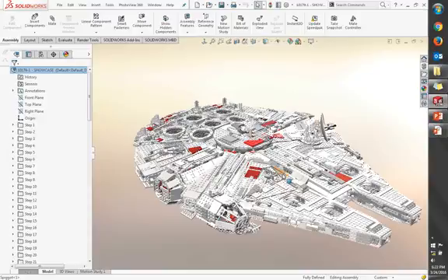So what I found out is that it's not so much a piece part count that you really run into. Really it comes into the mate count. And on this particular computer, when I get to about the 3,000 to 4,000 mate range, I see my computer take a huge dump. Now, 3,000 to 4,000 mates is only like a couple hundred pieces, really, if you're looking at it.